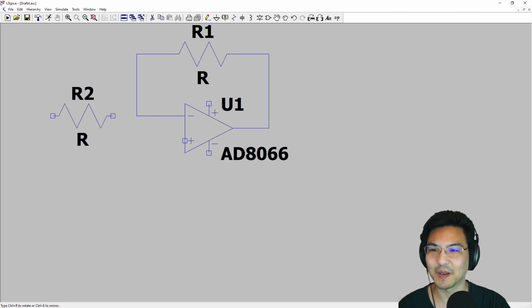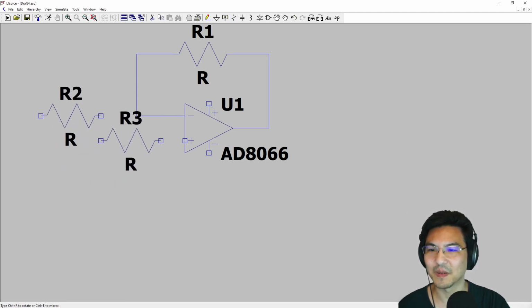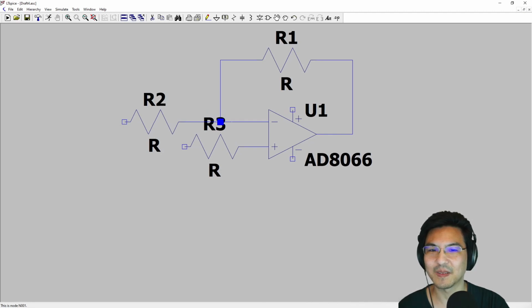So I'm going to rotate it. I'm going to put one feeding here and one where there's space here. Okay, so let me wire this here, this here, and the input is going to go to the one with the plus, the non-inverting. The other pin I'm going to just tie to ground here. And then right here's wire that. Oh, for the ground I just clicked right here.